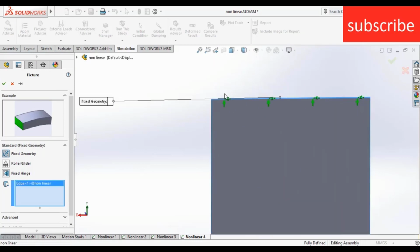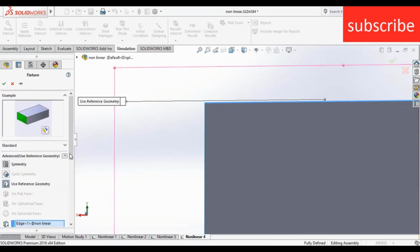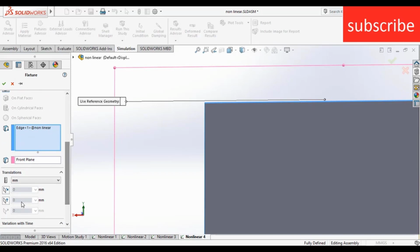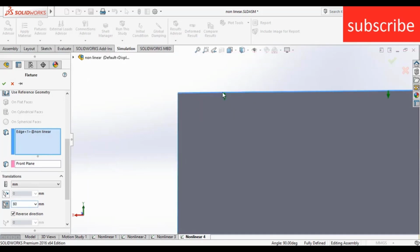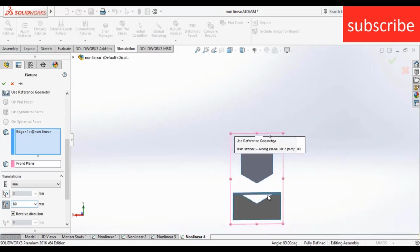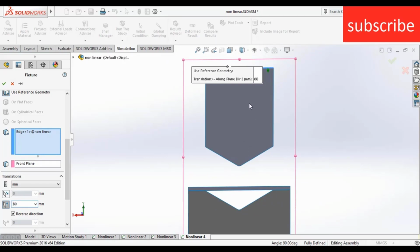top face. As you can see, the arrow is showing upward direction, but I want it to move downward. So go to advanced, click on this arrow. As you can see, the arrow is showing upward, so make sure you click reverse direction and enter the value of 80 mm. As you can see, the arrow is pointing downward, so this is basically what I want. So when I do the simulation, it will move this part by 80 mm. Remember, I maintained a distance of 100 mm while doing the assembly, so you need to do that.